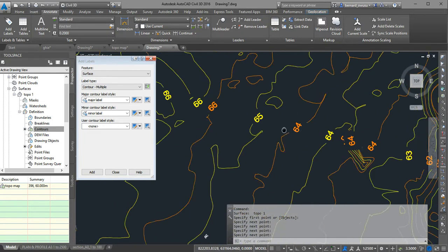And we said that the minor, we gave an interval of 0.5, but because the precision we have here is 0, we are not seeing the decimal, so we want to change the precision to 1. Now I told you to go to settings. We can also do it here. You can actually come here, click on this button and go to edit current selection.